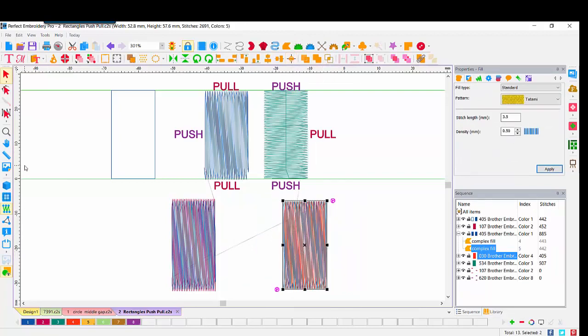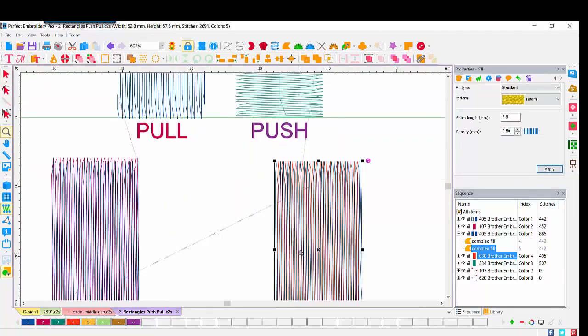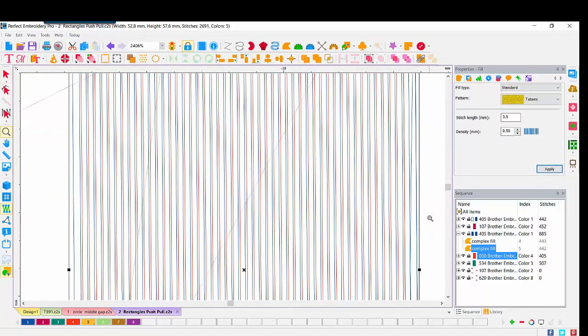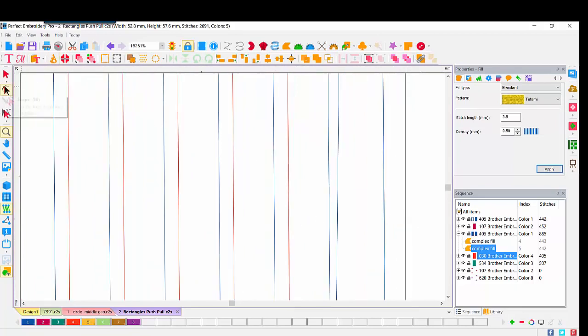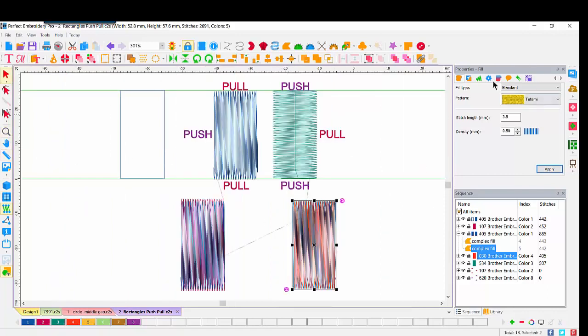They now align each other. We will zoom back in and take a look over here at the left. I'm really going to zoom in so that you can see when I do my measurement. And now if I pick my ruler, remember the orange one is the one that was changed. So if I click and drag all the way over to my edge, I can see that yes, indeed, that measurement is the 0.5 millimeter that I put in. So it did change exactly as we anticipated when we changed our properties.